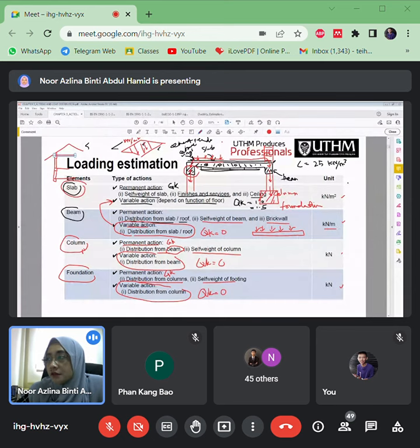And then if you make a sketch in 2D or 3D, this is the line for the beam all along here. This is an area for the slab, while this is for the columns here. That's why there will be a point load for the beams transferred to the columns, and also for the columns transferred to the foundations.